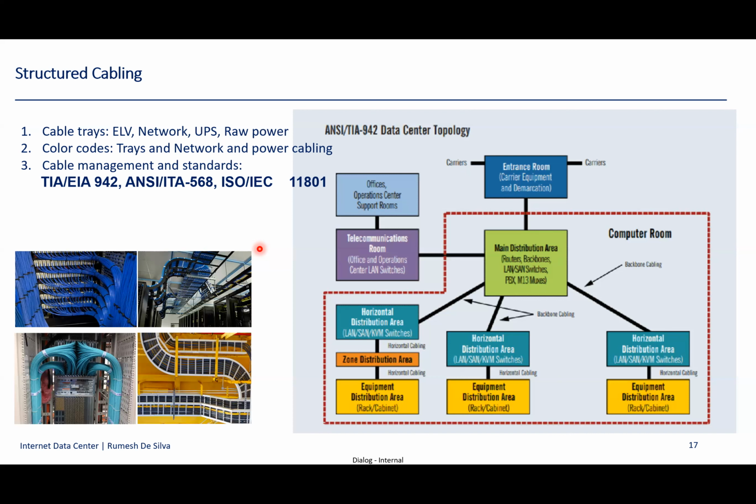And labeling is very important. Once you are laying a cable or plugging in some device, even power or network, each and every time you have to put a label according to the data center standard. Otherwise, it will be very harmful once you are working in critical scenarios, and downtime will be a real problem.